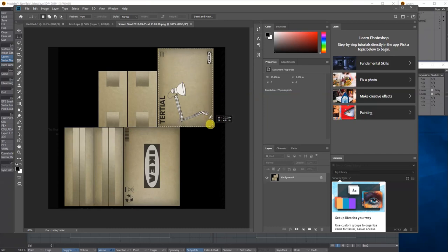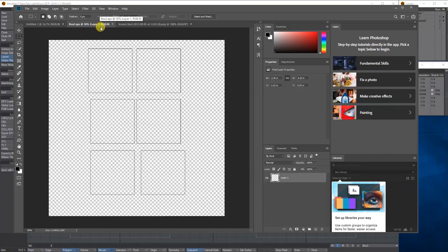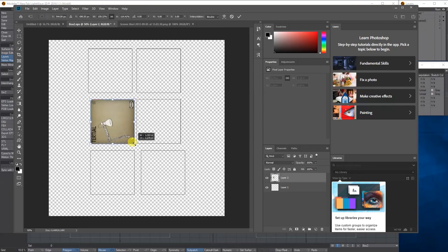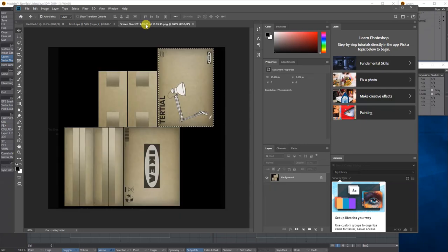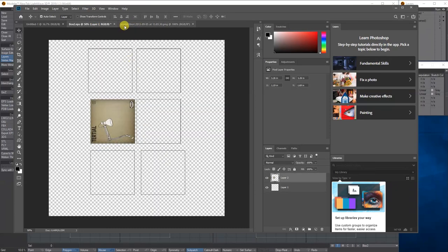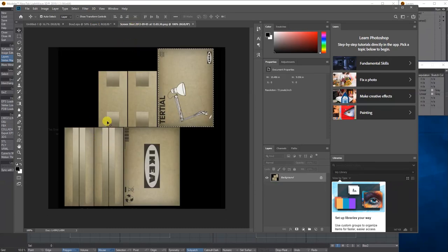So I'm going to select this side, copy it, paste it, and then what I'm going to do is, because I know these are, let me use this one because I think these are the sides. I'm not going to use the top, and then I'm going to free transform them out of proportion, but into this window like so. And then, like before, I'm going to repeat this and drag and drop each one of these into their own polygon panel.